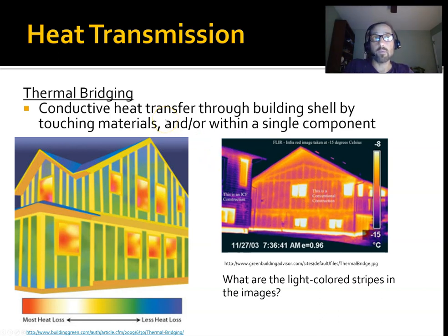That phenomenon is known as thermal bridging. You think of a bridge, a thermal bridge, right? Like a bridge for your heat, so to speak. So you have warm inside or outside, depending on the time of year, and the framing and other things like doorknobs provide this sort of bridge for the heat to travel from inside to outside.